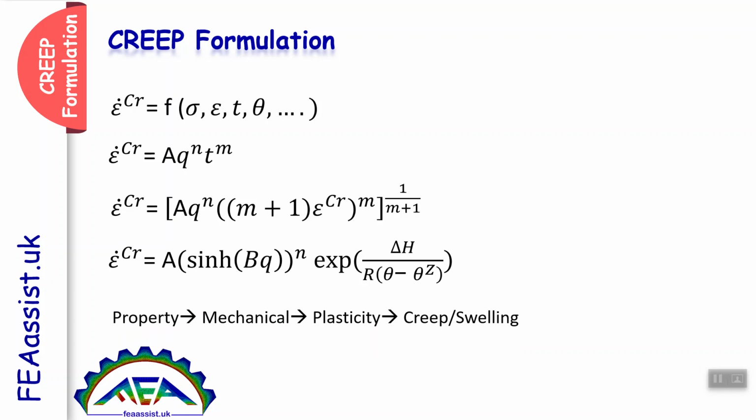But mostly you cannot predict the experimental behaviors, and you cannot fit the experimental curves by these equations. So you need a place to actually write your creep formulation there and force Abaqus software to solve the creep problem based on your new equation, which is not one of these equations. This place is creep subroutine.